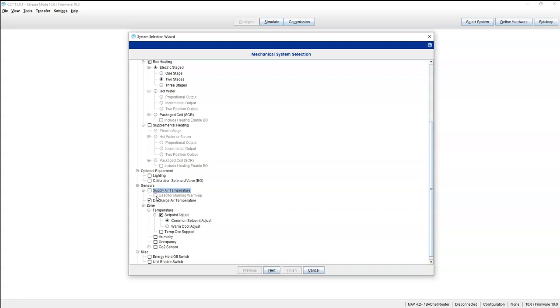There's a cost savings there. When it's only onesies and twosies VAVs warming up the space, then it's cheaper to just use electric strips in the VAVs. But when the whole building is cold, it's more cost effective to use actual air handler heating. So that's why you use supply air in morning warm up. Okay, so we got discharge air temperature.